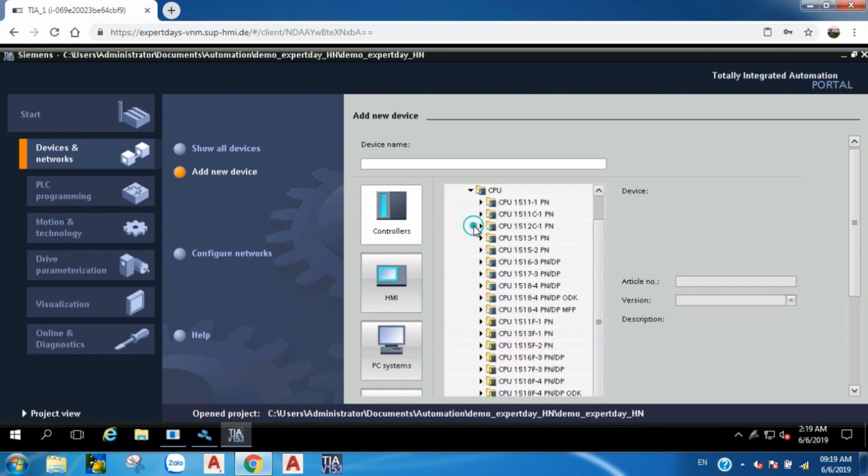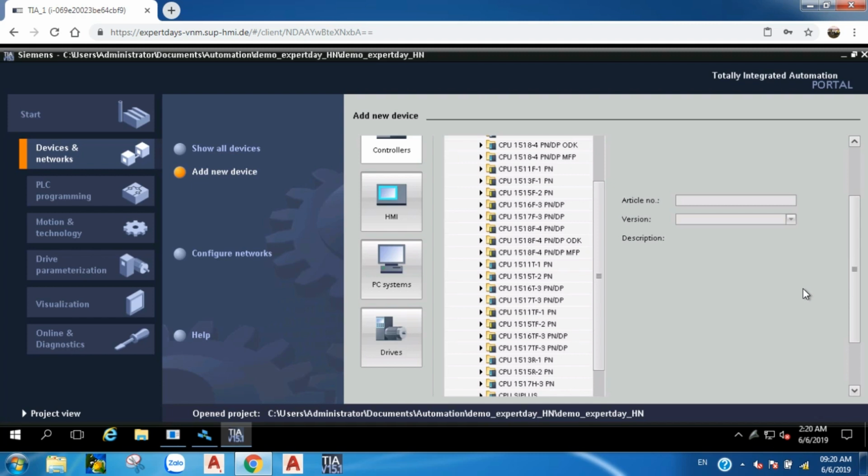You have 1513R to 1517H available. Oh yeah, here you see it. Here you see the complete system that is included, but it's actually in the network view. When you switch to the network view, you can see that within this whole system you have two PLCs. When you open the configuration, you can also see what I mentioned yesterday regarding the communication to WinCC, that you can activate down here: enable the system IP address for switch communication. Whenever you want this device to communicate with a non-relevant device, the system IP is used, also for the communication to a WinCC, for example.